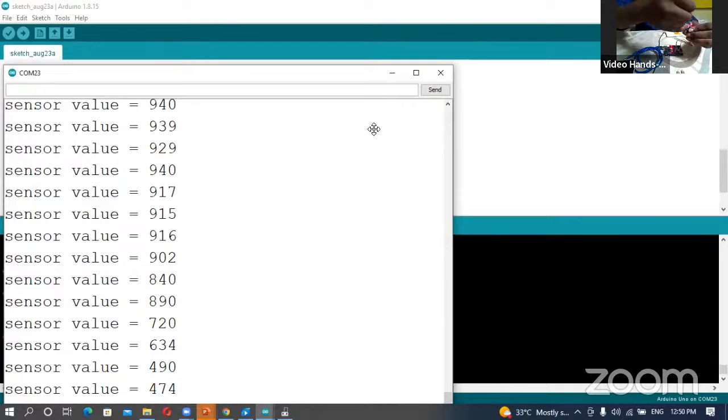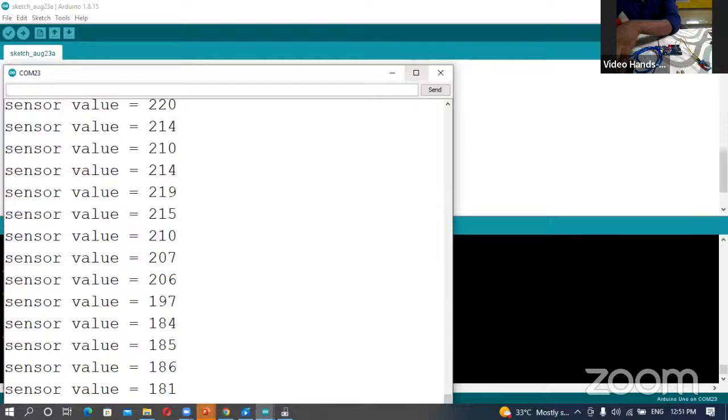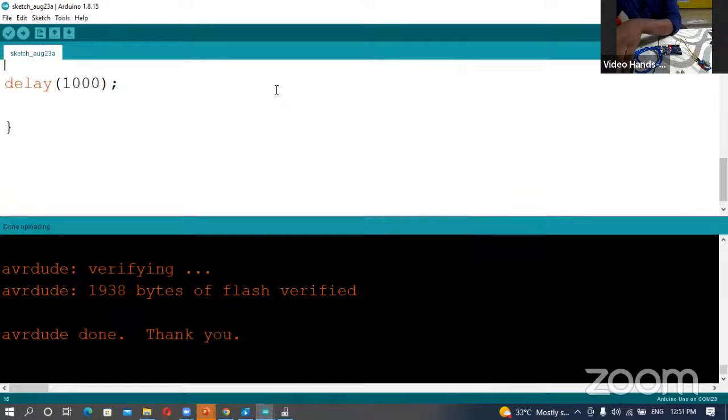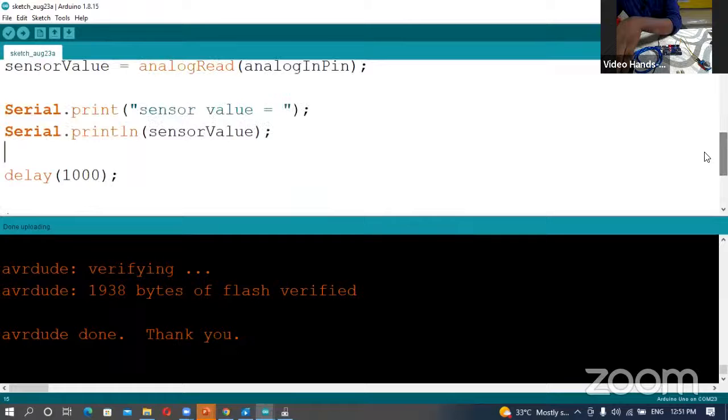Okay, that is for the digital signal, but in projects they never depend on digital signals. They depend only on analog signals for some threshold values. Our threshold value is greater than 700. Once the displayed value is greater than 700, this is called our threshold value. If our value is greater than 700, it means hazardous gases are found in our area. So now I am presetting the value. Now I am fixing the threshold value here.